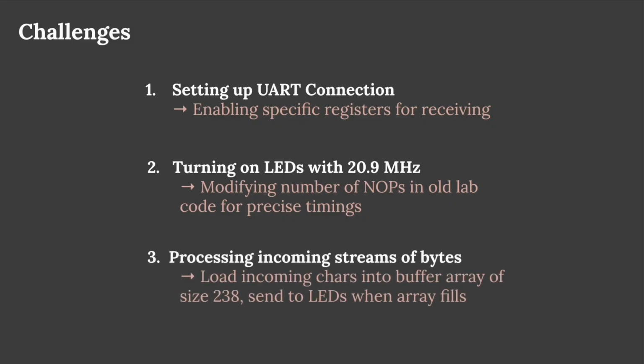Lastly, we had to process incoming streams of bytes. This meant we had to load incoming characters into a buffer array. And once that buffer array was full, we would finally send that information to the LEDs and actually light them up.